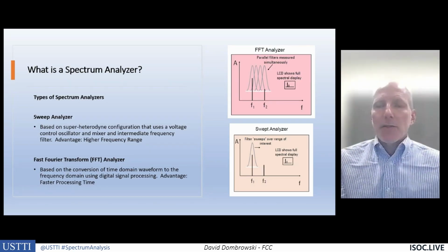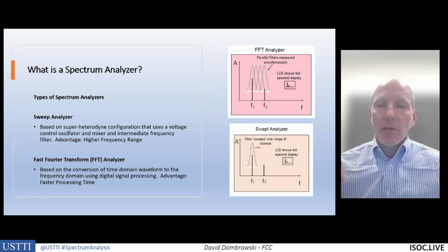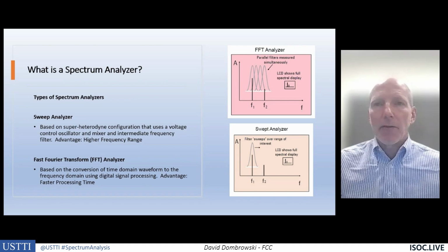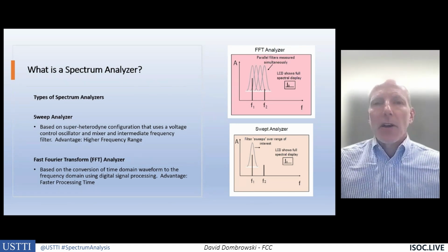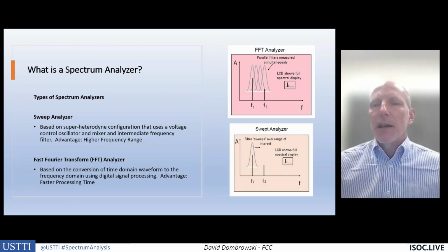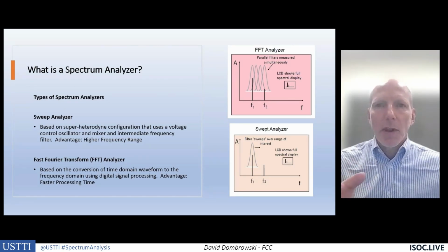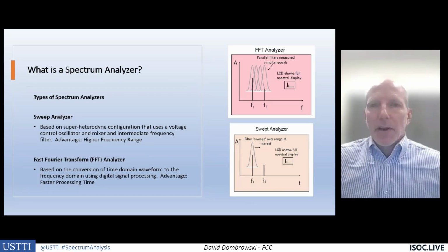Yes. We connect spectrum analyzers to our satellite dishes. We have a group that's right on the same property as where I'm located today in Columbia, Maryland. We have six satellite dishes, and they are connected to the spectrum analyzer. One of the things we'll talk about in a few more slides is the sensitivity of the analyzer. How low a level of signal can we receive? We can also improve that by installing high-gain antennas and with amplification, and we're able to pick up those low-level signals originating from satellites that are thousands of miles up in space.